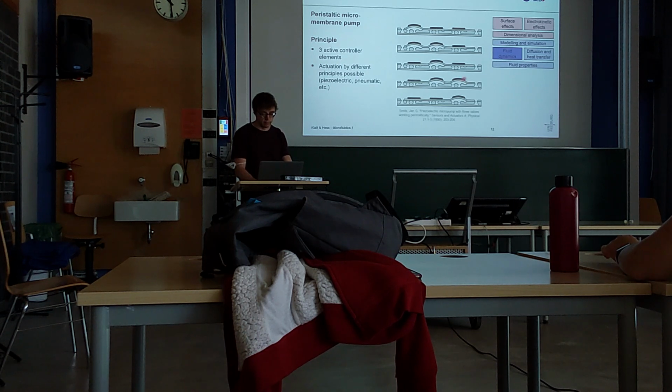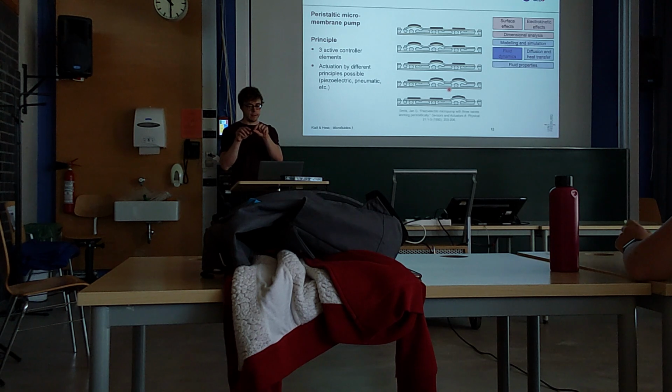You then open the right controller, and I guess now you really see that by pushing down the middle controller, you can push the liquid through your system out to the right direction. So if you want to simplify this concept, you can think about a tube that is fully filled with liquid. If you squeeze it in one position and move along the tube, you will just push the liquid out of your tube. And that's the same concept here, except that it's not continuous, but that you have three defined volumes or valves that you use to push the liquid out of your system.